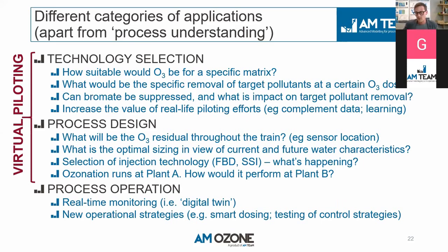If you look at regulatory compliance operations, smart operations based on the matrix and things like that. So smart dosing, the testing of different control strategies, because Sumo, this platform, allows to integrate controllers. We have not gone in there because we want to keep the complexity limited, but you can control the plant also in this virtual platform, so you can experiment with control strategies. So let's go back to Giacomo now, and he will be showing a dynamic simulation, which means that the model is being fed with real plant data of a very long period of time.